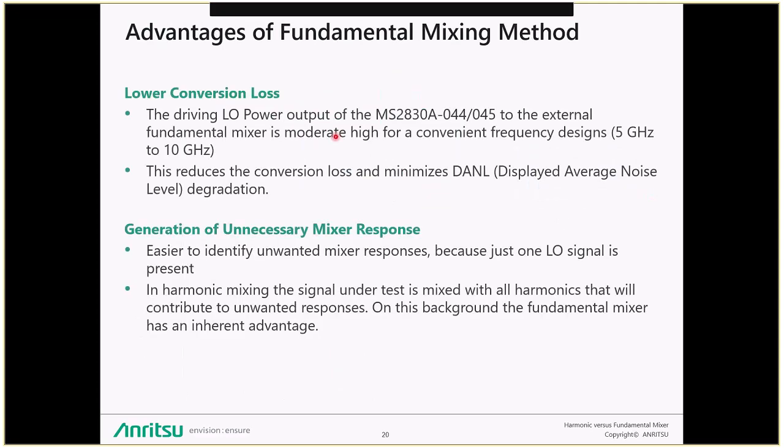So the advantage of fundamental mixing is basically a lower conversion loss. The driving local oscillator power output, instead of being quite high, is, let's say, moderately high for convenient frequency designs. And this will reduce the conversion loss and will minimize the DANL, the noise level degradation.